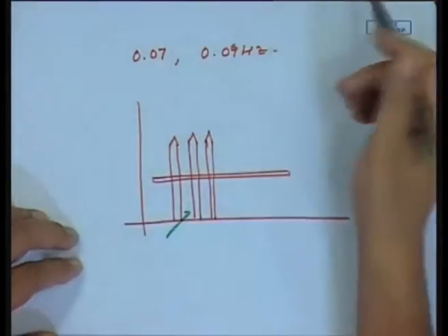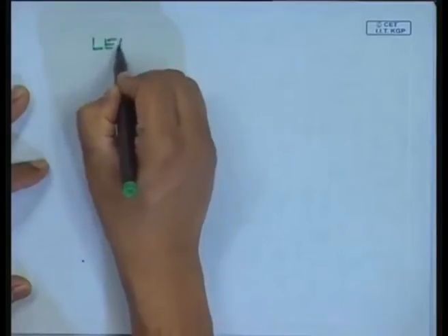So, this is what is known as the picket fence effect in FFT. So, once we have a finer resolution, we are going to catch the signal. So, this is to be avoided by having adequate frequency resolution by increasing the number of data points.